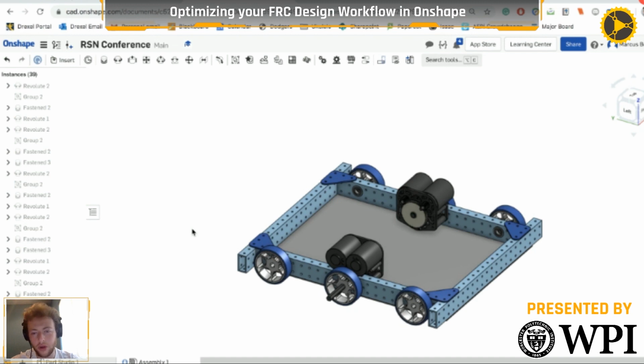The assembly won't translate quite right. The individual features won't totally copy. It's not going to grab the specific extrude and revolve and fillet that you made, but I believe the geometry will copy over, and the assembly, at least left in place, will copy over.